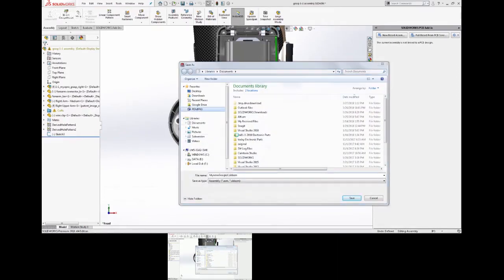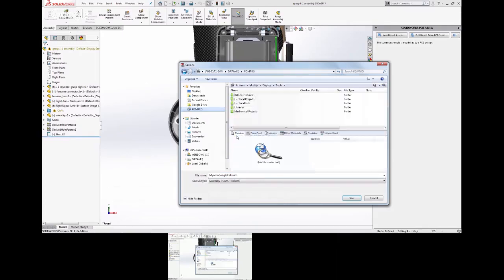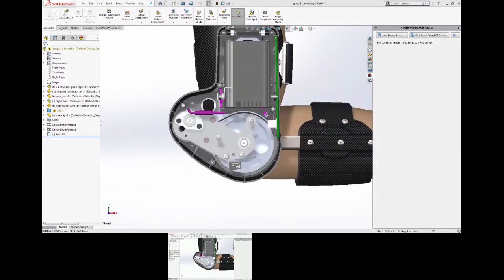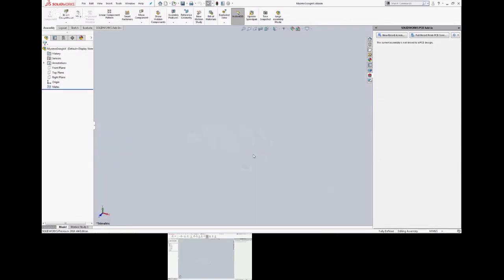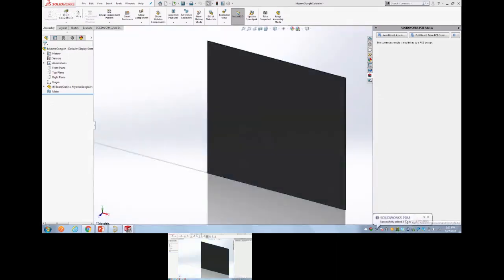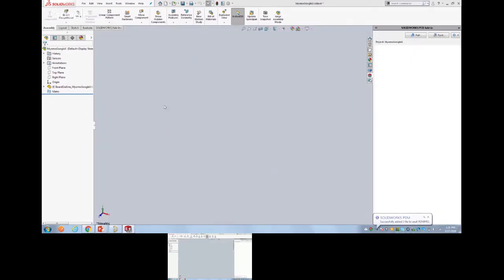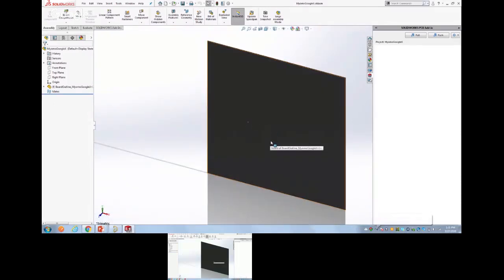Perfect. So here, I'm going to use PDM to save the mechanical assembly. There's nothing different from how the mechanical person does it today. This is a mechanical assembly. I'm going to point to my mechanical project, and this is the name of the assembly. And this is the intelligence of the collaboration. It's going to create a default 10 by 10 PCB. Notice that this PCB is now represented in your feature tree. It's getting checked into PDM, being hidden here. It got checked into PDM automatically. And then, boom, I have a 10 by 10. That's the default board in Altium Designer, a 10 by 10 default PCB.